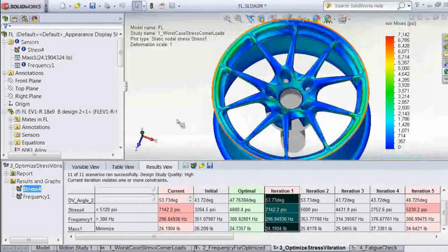So, what is fatigue? Well, fatigue is essentially, I didn't bend it, but am I going to break it? And then the inputs to fatigue are the number of cycles. So in this case, if I want to add an event, I could add multiple events and sum up multiple analyses. We see here that I have an opportunity to put in the number of cycles, and then I pick the stress analysis that I'm using to define that event. So we've already done that, and we've defined our material properties for the fatigue analysis.